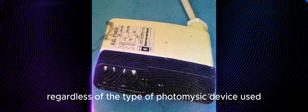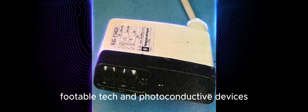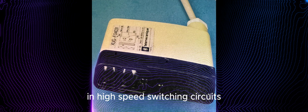Regardless of the type of photoemissive device used or the type of circuit it is used in, the greatest advantage of the photoemissive device is speed. The photoemissive device can turn on and off in a few microseconds. Photovoltaic and photoconductive devices generally require several milliseconds to turn on or off. This makes the use of photoemissive devices imperative in high-speed switching circuits.